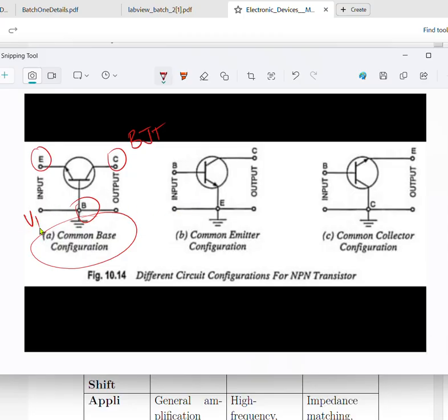And there is a VBE which is set. Okay, if we establish a VBE, it will basically transmit and there'll be an amplification. Holes will transmit or electrons will transmit respectively. But over here, the emitter is down, so it will basically become VEB. So there's an opposite effect here. If we increase VEB, then instead of more current happening, it will be less current happening. It will have an opposite effect here. Here it is VBC.